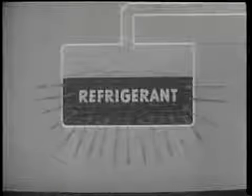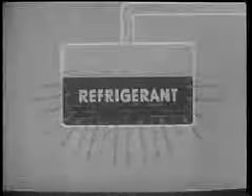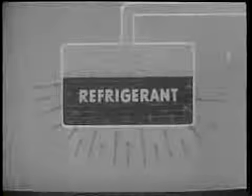The principles of refrigeration are physical principles applied as follows for the purpose of removing heat and reducing temperature. First, mechanical refrigeration rests on the ability of a refrigerant to absorb heat while changing from a liquid to a gas, and to release that heat while returning to the liquid state. Second, when the pressure on a liquid refrigerant is reduced, the liquid boils at a lower temperature.